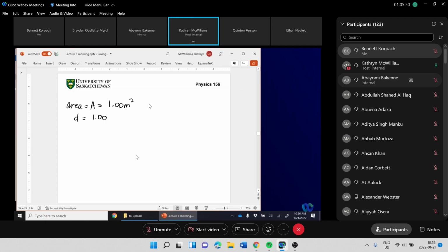If you can get a high enough electric field that can essentially separate electrons from their atoms in whatever material is between the plates, air, plexiglass, whatever, it can break it down. When you're designing a system, you would always put in a margin of safety and make sure that your electric field and voltages never get that high. Right, okay. Thank you.